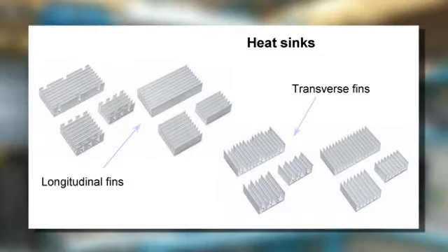Once the thermal parameters of the design have been calculated, that means the temperature increase and the power dissipation, and once the surrounding conditions are known in terms of, for example, airflow and ambient temperature, it is possible to choose the proper heatsink either from the assortment that Vicor offers in terms of accessories or from third-party manufacturers, which offer a broad range of different shapes and sizes of heatsinks that could accommodate any kind of application.